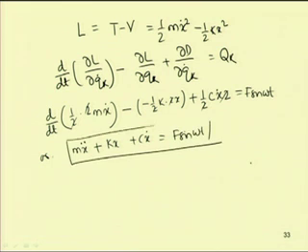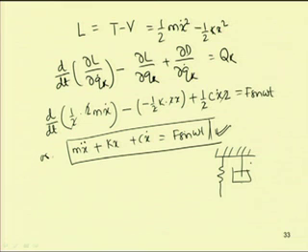So this is the same equation we derived before by using Newton's second law. By using Newton's second law, or by using the Lagrange principle or Hamilton principle, for a simple spring mass system you can derive the equation of motion in this form. Here we have taken one linear spring. The spring can be made nonlinear for the case of a nonlinear system.